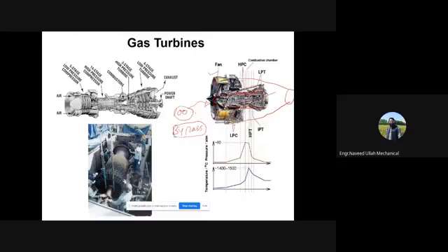What do you mean by this bypass ratio? Let's say for example, it depends on engine, okay? We have actually 10-90, 20-80, 40-60, 50-50 bypass ratio engines are available. But let's say for example, here 30% of the air out of 100, it is coming here, and it takes part in the conventional compression process, combustion process, and then expansion process in order to produce work, okay? And the exhaust will be delivered here, right? And the rest, 70% of the air, it is just bypassed.